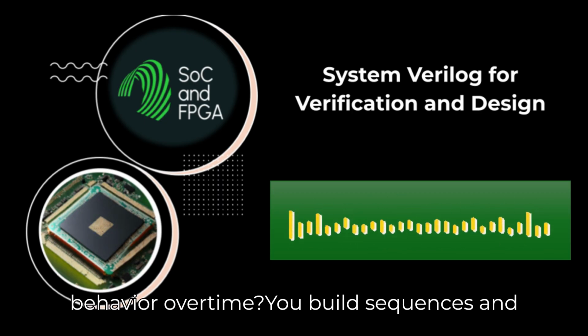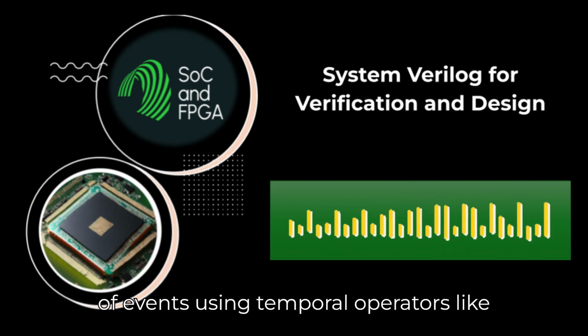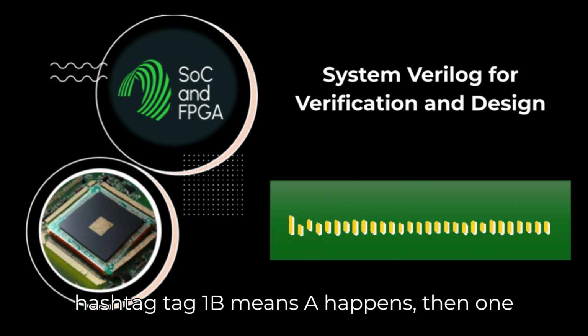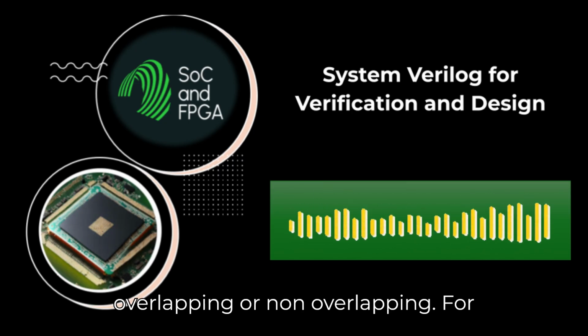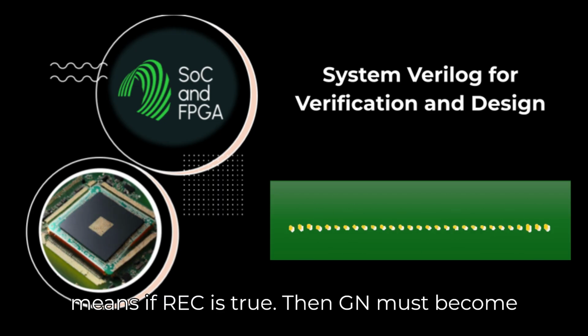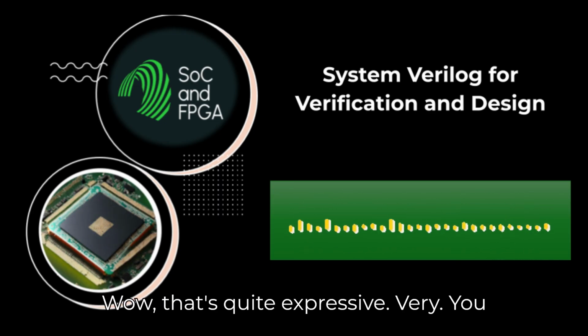How do you define behavior over time? You build sequences and properties. Sequences describe patterns of events using temporal operators like ## for clock cycle delays. So A ##1 B means A happens, then one clock cycle later, B happens. Properties then use these sequences, often with implication operators, like overlapping or non-overlapping. For example, req |-> ##[1:5] grant means if req is true, then grant must become true between 1 and 5 clock cycles later. Wow, that's quite expressive.